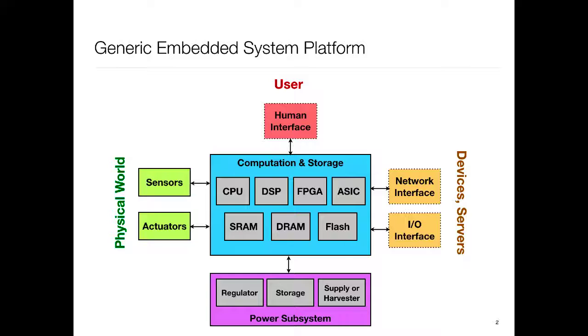On the car side, there's something called CAN, Controller Area Network, which is used quite heavily, and the industry is in the process of transition to gigabit type network interfaces. Not all cars use these, but Teslas, for example, use Ethernet. So we see these domain specific things as well. So, rich stuff on the networking side, and likewise I/O interfaces. By I/O interfaces, I basically mean how peripherals such as sensors and actuators might get connected.